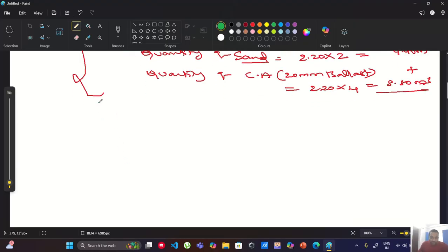In the starting I explained the standard parameter, quantity of steel for 1 cubic meter in kgs. I already explained. Now we have to consider quantity of steel. We are calculating the beam here. So quantity of steel for beam per 1 cubic meter I am considering 1%. In the standards I already explained 1 to 2% for the beam. Now I am considering 1% as the quantity.